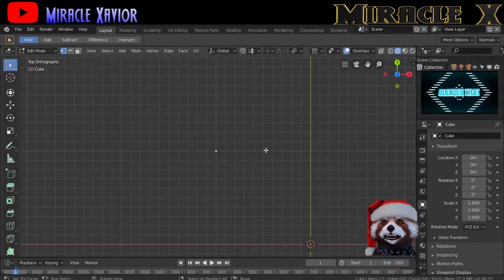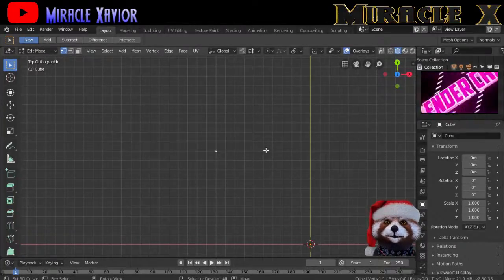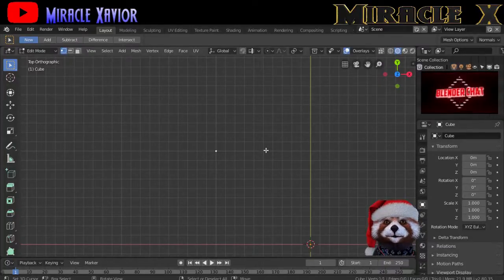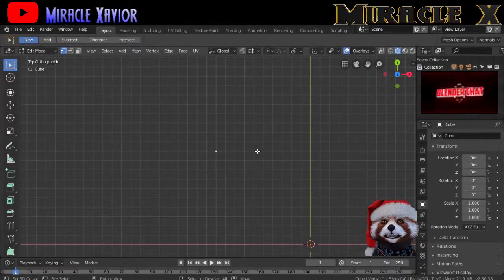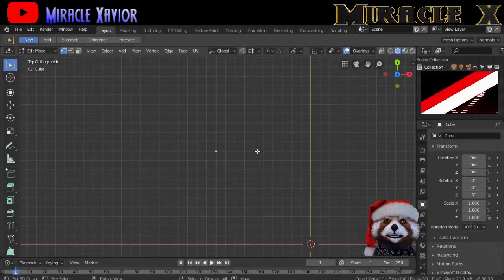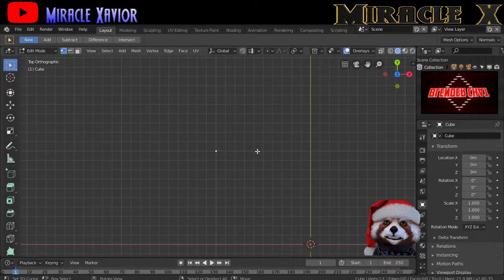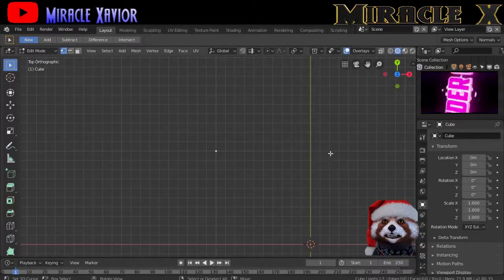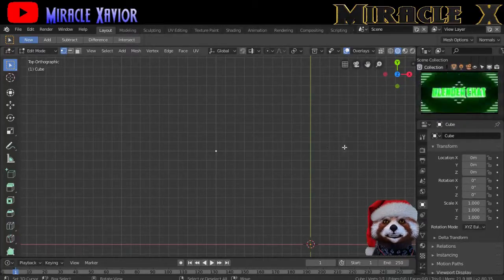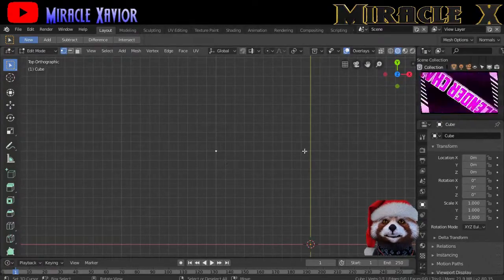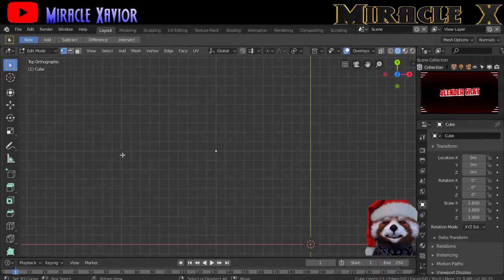And to do that, you have to type in the coordinates of where you're going. So you say line, it's L, and then the direction is the x-axis. If you're going towards the right side, positive; left side is negative.